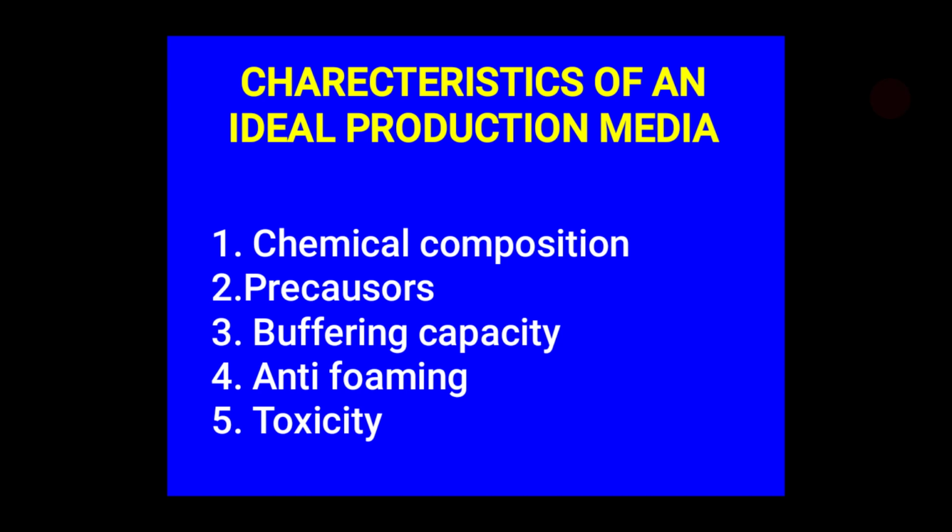So this should be used for controlling the foams, and the anti-foaming agents may be added at the stage of the media makeup, meaning before sterilization, or they may be incorporated after sterilization, or during fermentation also, if it is required. Okay, so foaming is an important problem in the fermentation industry. So addition of anti-foaming agent is desirable to carry out a successful fermentation process.